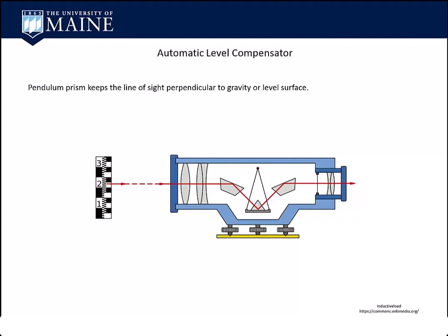As it goes out of level, or perhaps wasn't leveled properly, to an extent, it will correct with those prisms and the hanging compensator, because it's free floating. As the instrument might go out of level, it will compensate to a certain point, and that doesn't mean you shouldn't be keeping an eye on it, but there's a little bit of wiggle room in there for you.